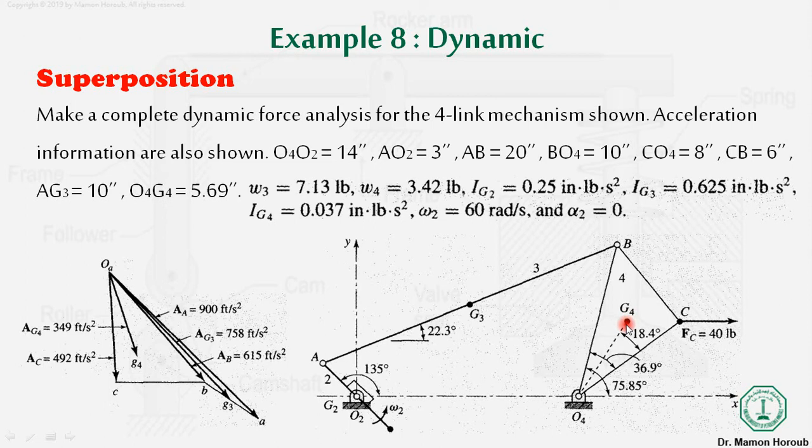the inertial force due to the acceleration AG4. And we will consider the reaction forces when we consider only the inertial force. We will not consider this one. Similarly, the third case will be when we will not consider this force, and also we will not consider this force, and we will just imagine that this body, link 4, is interacting with link 3. So what will be the reaction forces? So the force analysis of this one link will be a summation of the 3 force analyses. We will see it in the coming slide.